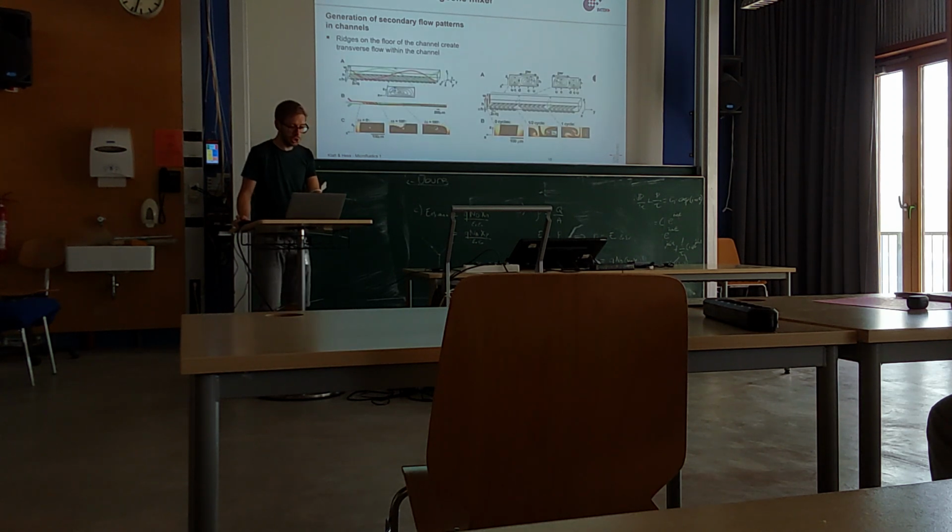And the second approach, which uses basically the same principle, and which is very common in pressure-driven systems, is a staggered herringbone mixer. And it also relies on the same principles. So again, we want to create those secondary flow patterns, and this is achieved by not having a smooth bottom, but we have those kind of ribs you can see here, and those ribs induce some complex pressure field, and this pressure field then leads to the formation also of vortices. You can see this here.